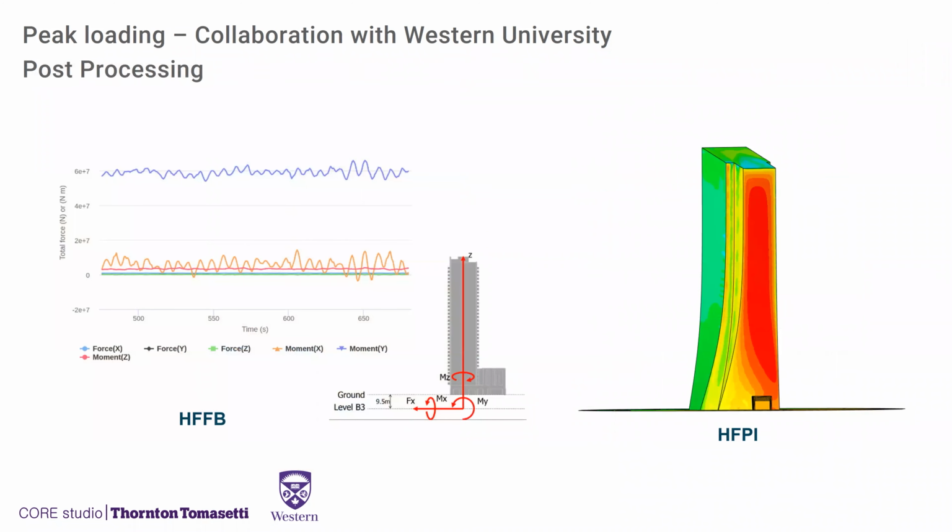And then actually, I'll get a bit more detail into the digital wind tunnel and what we want to do with that, but it's also actually the post-processing. So from the pressures of a CFD simulation, getting that back into the structural analysis toolkit of actually pressures on the building, or base moments and base forces. So we're working to integrate that all together.